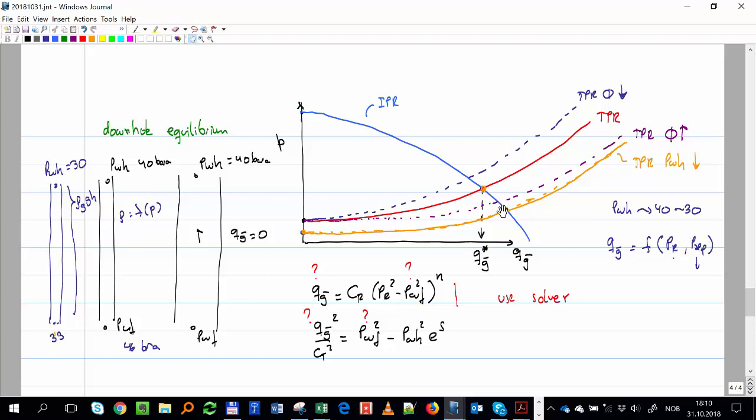So you know that the intersection will be to the right of this point because I'm going to have higher rate. Now, to know how the curve will look, I also want to find the origin. If I have 40 bar, the red curve, and no flow, maybe I will have here 46. The density of the gas, let's say something like, I'm not sure about the number, but let's say it's 20 kilogram per cubic meter.